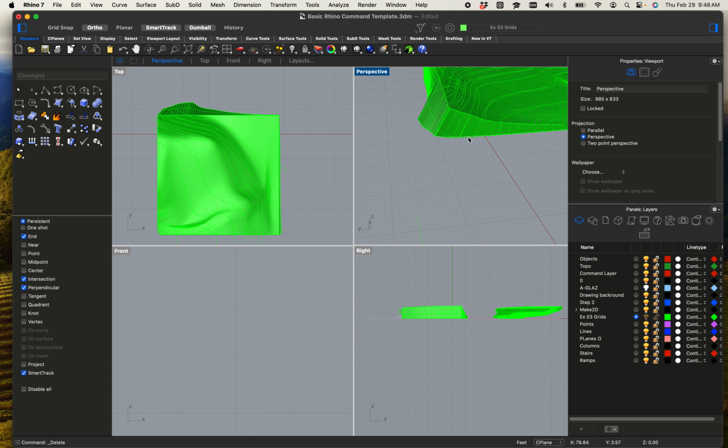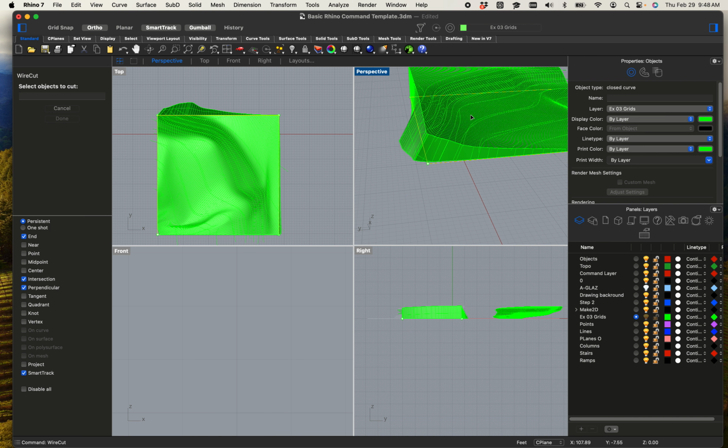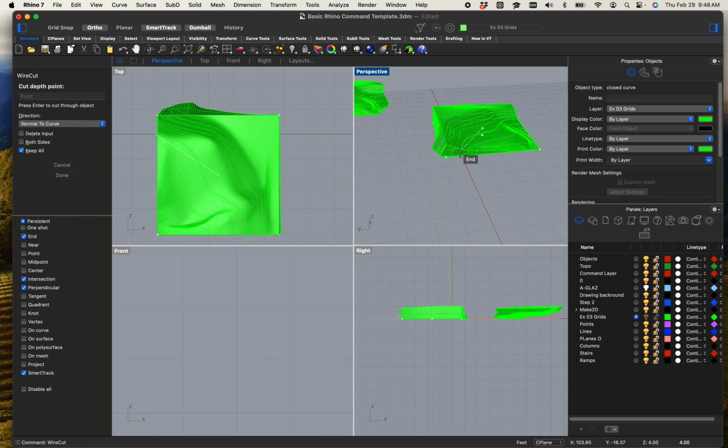Obviously, I can chop it off here, so I can use my square. Wire cut. Now, as we know about wire cut, let's see if this actually works, because my line is unfortunately right on it. But yeah, basically using that initial square that I drew, basically chopping off this little extra. Thinking about it, it might fail because, again, you can't usually have the line on the object. So I'm going to cancel it if I can. Please don't freeze. Don't do it. Don't go towards the light.